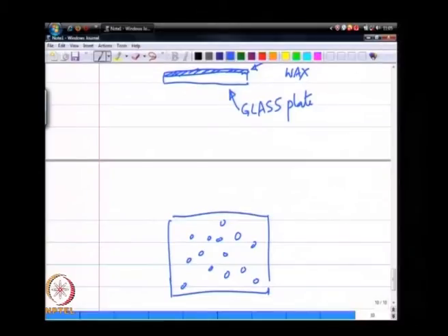Okay. So, once you have recovered this plate with all these indentations on it, you can then go to each one of these indentations and measure the size, either under a microscope or just by placing it against a known measure like a ruler.